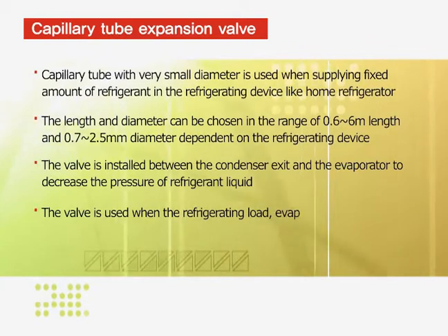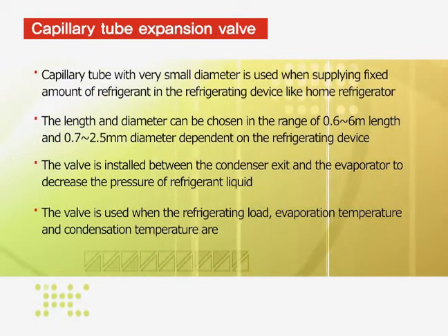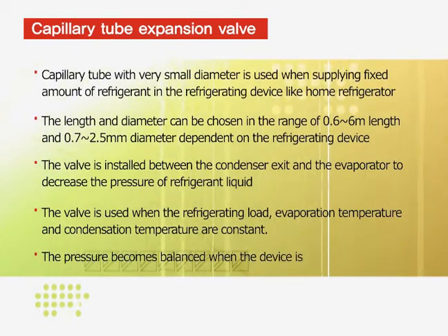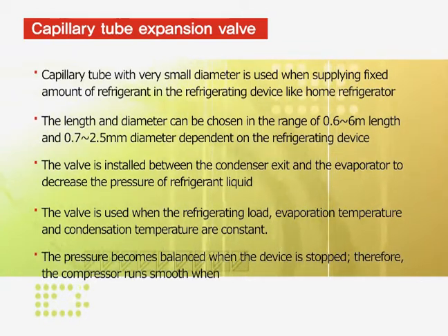The valve is used when the refrigerating load, evaporation temperature, and condensation temperature are constant. The pressure becomes balanced when the device is stopped. Therefore, the compressor runs smoothly when restarting.